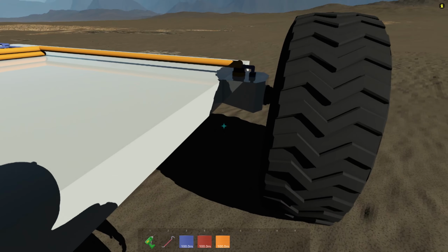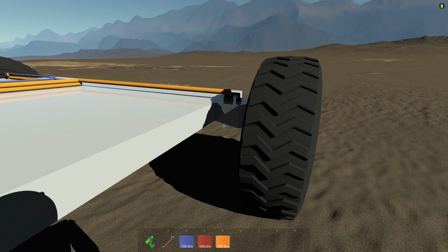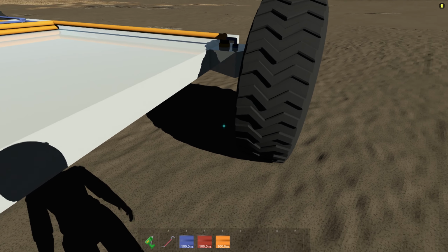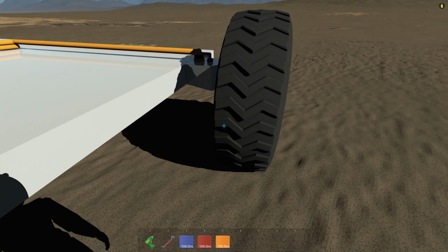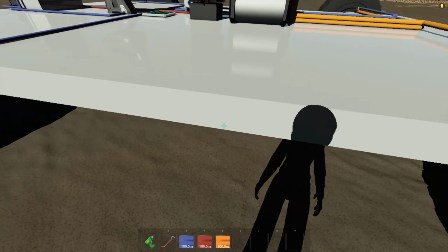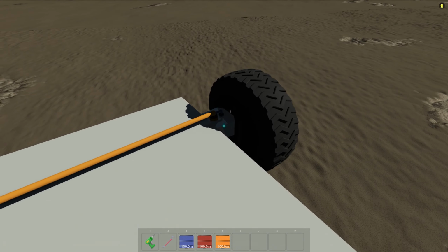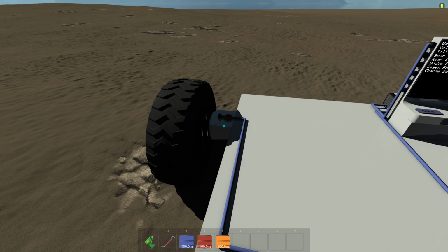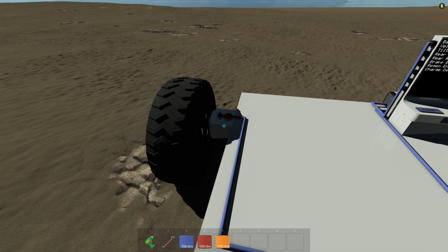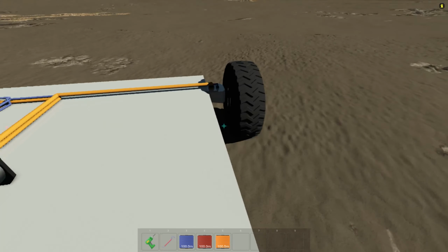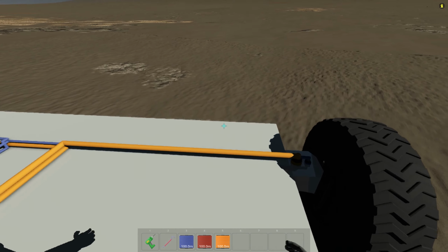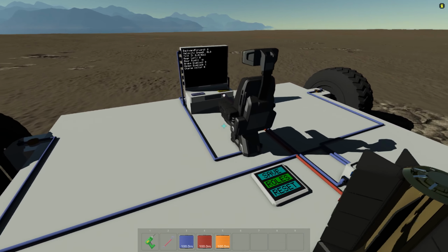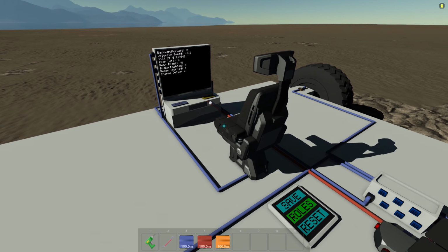I guess in theory you could put a sensor on the bottom here that reads the distance between here and the terrain. If it's really in the air, you'll know because it's real close. There's probably a little area where it's just off the ground, but you won't really know. That's a workaround, but we're hoping we'll get suspension loading added to the wheel property so we can pull that out.